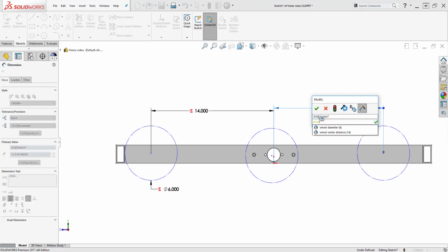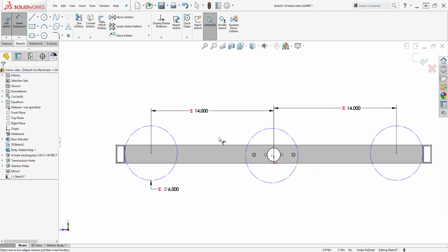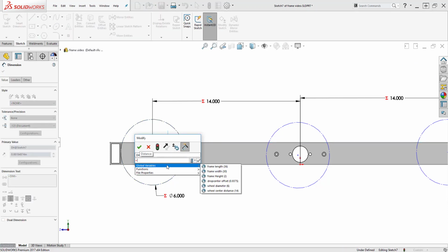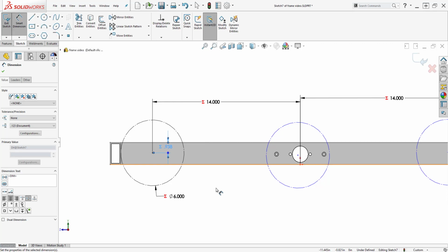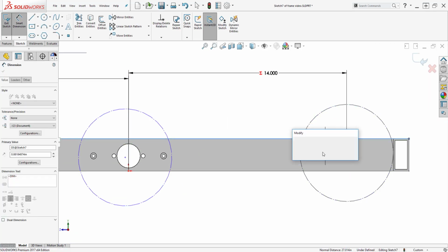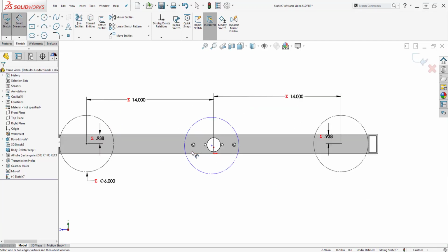At this point, I'm also going to go ahead and add my 1.5 inch holes. Since you most likely bought a hole saw or a cone bit that's 1.5 inches in diameter, I'm just going to go ahead and use this same universal size so you don't have to buy another tool. As long as this hole is approximately where the axle needs to go and you leave enough space around it, and you also consider the drop center, this diameter will be more than enough clearance so that you can still adjust and tighten the chain later.